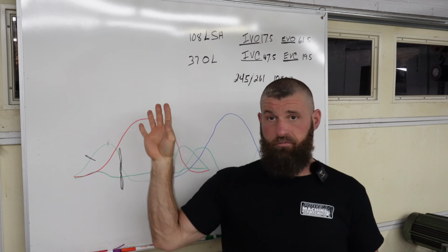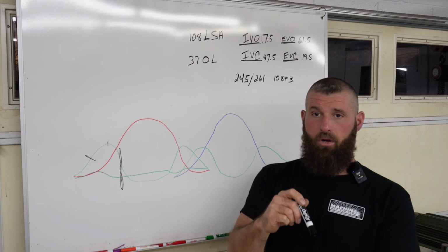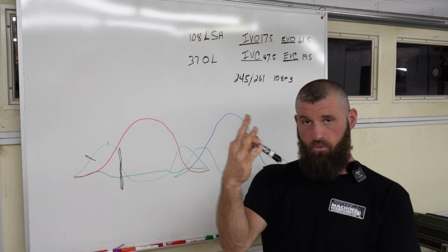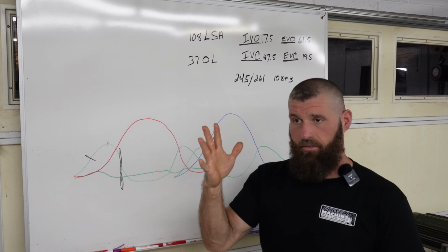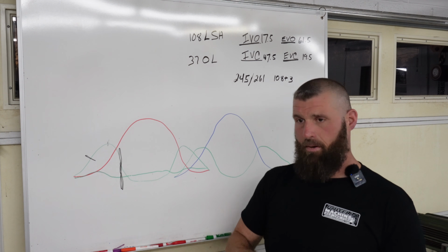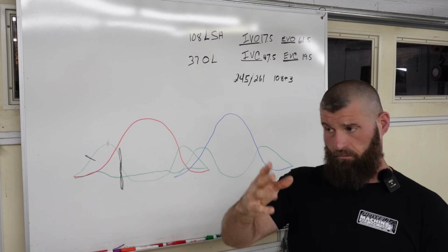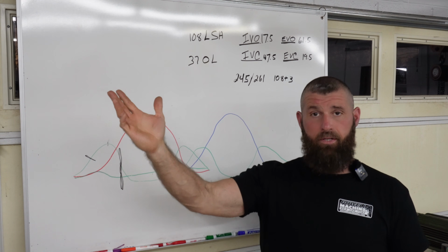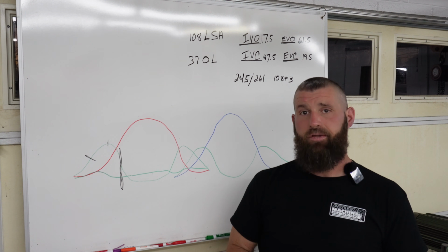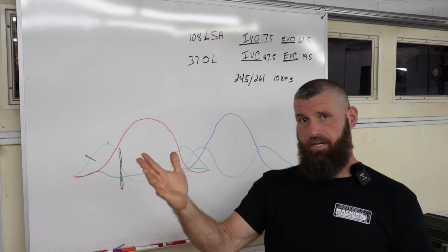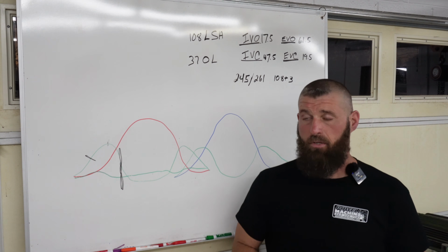So that's the parameters for intake duration, and that's exactly what we did for Bob. We took his cubic inches, we took his RPM, and we took his available cylinder head flow. And we crunched a bunch of numbers. I'm almost positive he told me he was going to go to about 6,000. He wanted to shift around 6,000. And usually, depending on cylinder head, they'll carry 300 or 400 RPM. I think his carried another 250. So it was on the lower end, but again, he's out of cylinder head. So the math yielded 245 degrees, right?